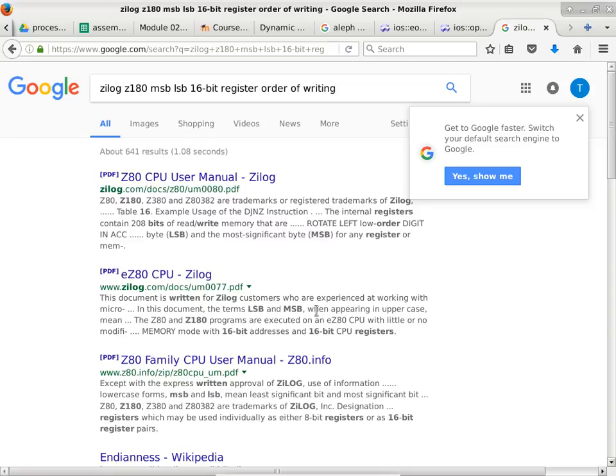You don't see an error because it works. You do not see an error because the propagation delay made it seem that it's working. Because the race, the correct component wins the race in that case. Okay, so it appeared to be working even though it's written in the wrong order.